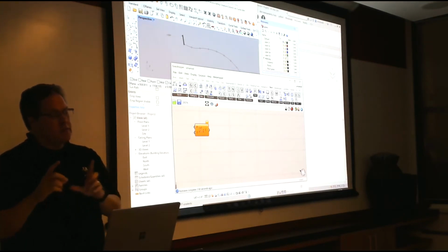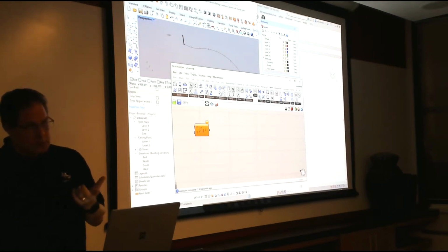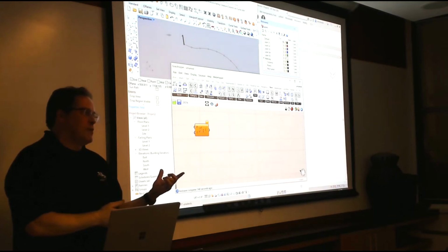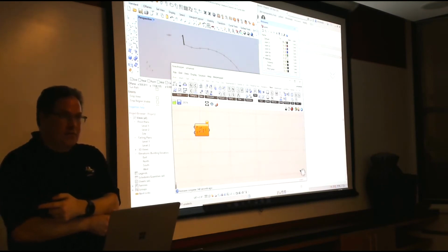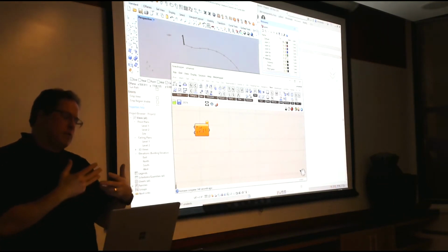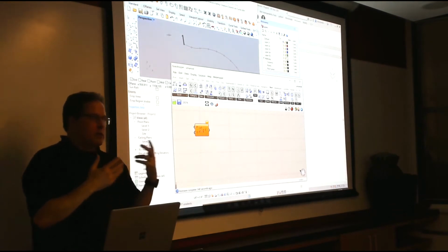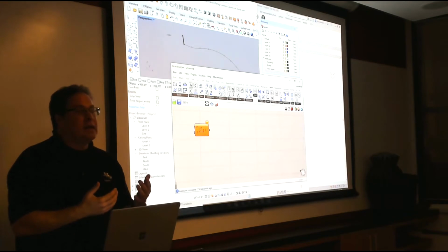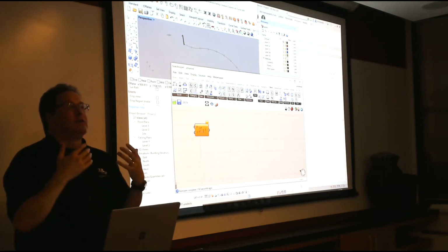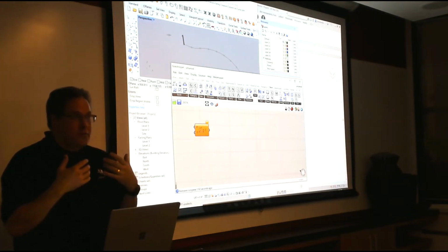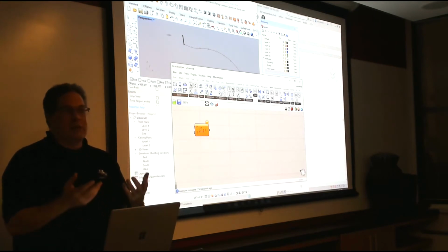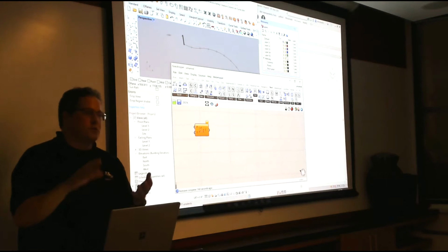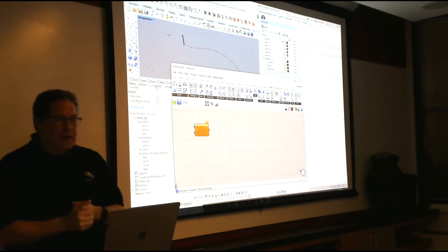Now, if adaptive components get too slow, which can happen, then all you do is generate the facade in Rhino and wrap it, its families going across, right? So we have all 3 strategies based on the complexity and where you're going with it. All of them end up in good family categorization in a way that they slice correctly, they schedule correctly, all that kind of stuff.